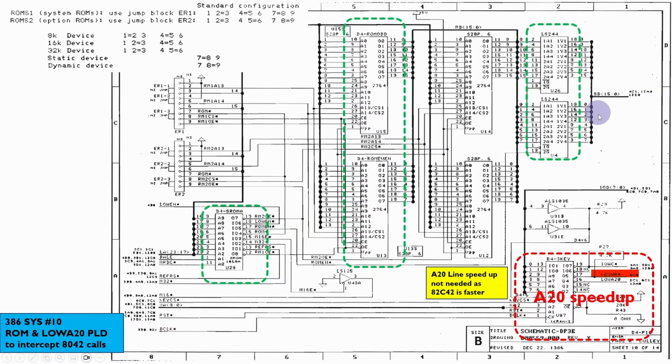So again, the key thing here is that this is going to be testing our 16-bit data bus and all of the mapping and the translation carried out by the logic, because the ROMs don't go directly to the 32-bit data bus. They go through all of that logic that we've been working on for the last couple of videos. And you'll also notice over here that there are quite a few jumper settings on the original DeskPro.